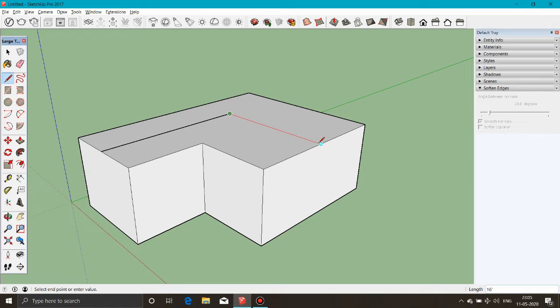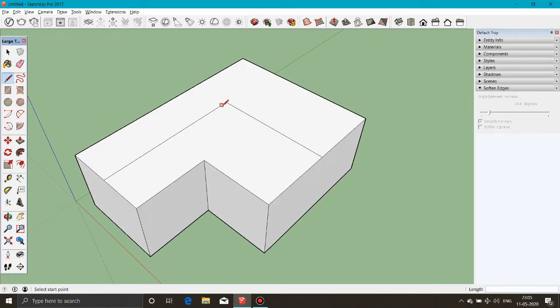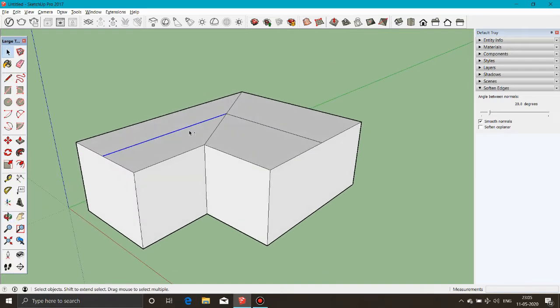Now that we have both ridges in place, simply draw the line where the roof will fold when we move the ridge lines. Use the Select arrow and click on one of the ridges. Then, hold the Shift key and watch the icon. There is now a plus/minus that indicates that you can add to, or subtract from, your current selection. This allows you to select other entities and deselect them as well while holding Shift.